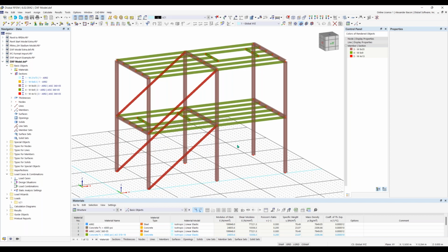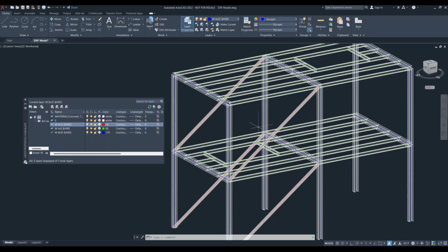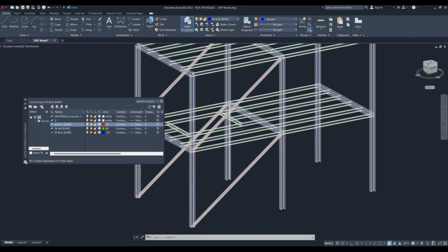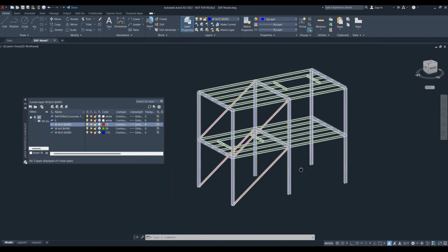And this isn't suitable for everyone. Since you have to create the analytical lines in AutoCAD, if you haven't already done that, it might be a lot of work, and maybe you're better at modeling them in RFEM. But it might be helpful for companies that use blocks in AutoCAD, maybe use very similar structures, and maybe the same type of structure all of the time. And if in your blocks you already have the analytical lines modeled, then this could be a really easy solution for you.